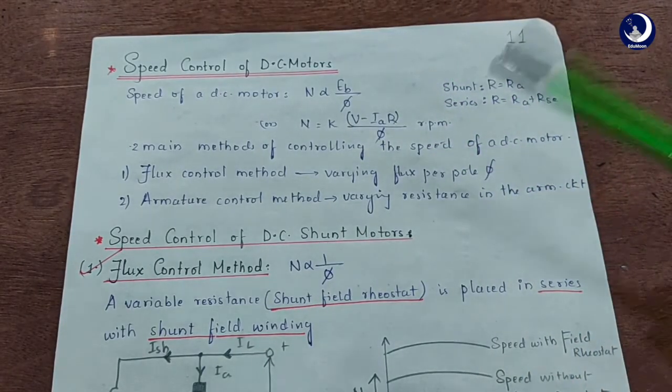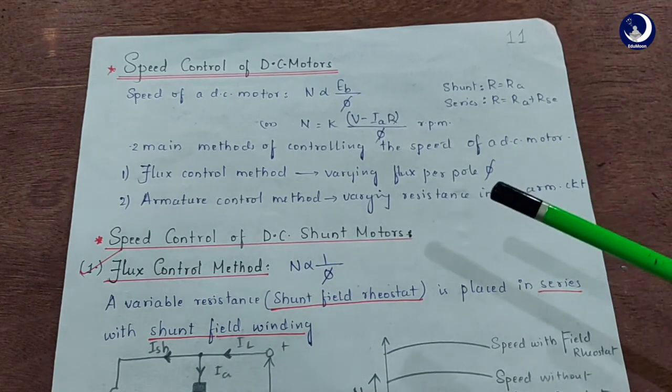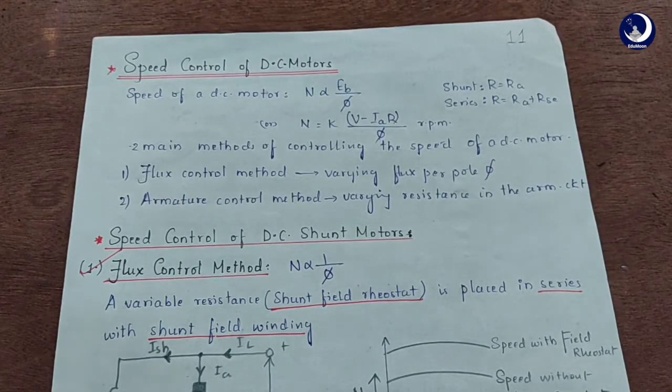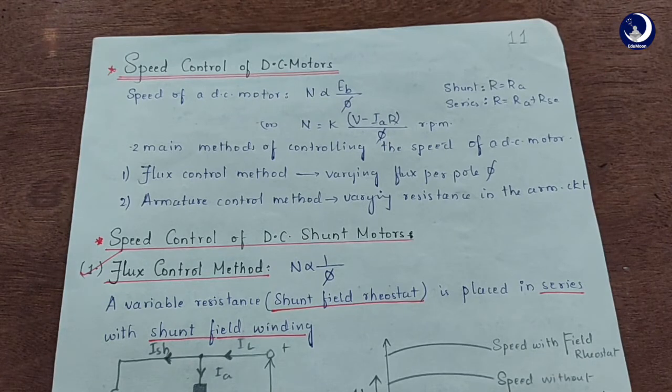Although a greater percentage of electric motors in service are AC motors, DC motor is of considerable industrial importance. That is because the principal advantage of a DC motor is that its speed can be changed over a wide range by a variety of simple methods. Such a fine speed control is generally not possible with AC motors. In fact, fine speed control is one of the reasons for the strong competitive position of DC motors in